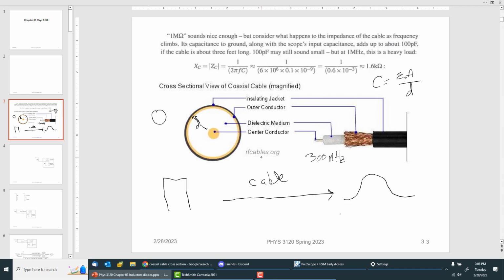They're not any bigger because even at 60 hertz, once you make it an inch in diameter, there's no current in the middle because of the skin depth. You'll learn about that in E&M. For us, it's about the capacitance, the stray capacitance, and you notice that if we get up into 1 megahertz, we're already loading down our system.